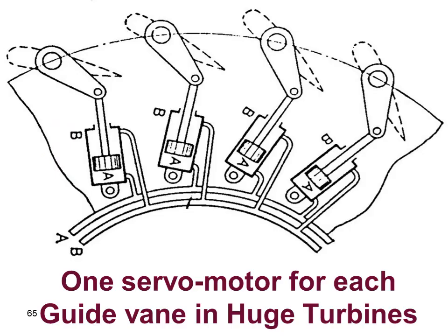In this figure, we can say that it's a huge guide vane, and we cannot operate all the huge guide vanes by two hydraulic cylinders. As in the previous slide, for a huge turbine with huge guide vanes, each guide vane will be moved by a single hydraulic cylinder fed by high pressure at A and low pressure at B from the same line.